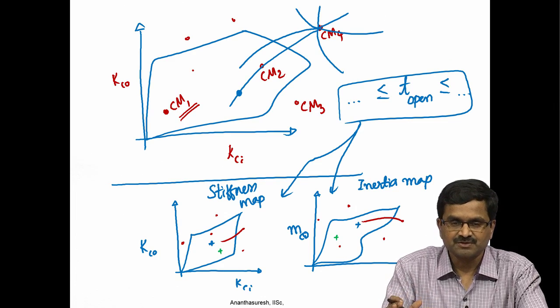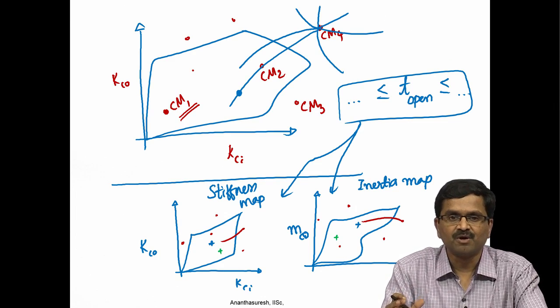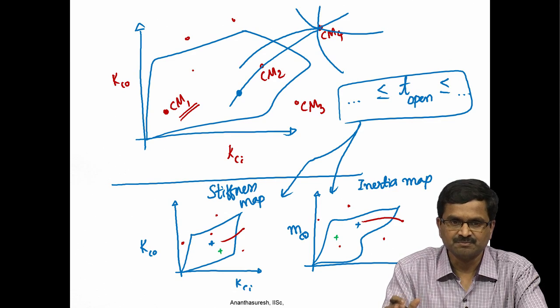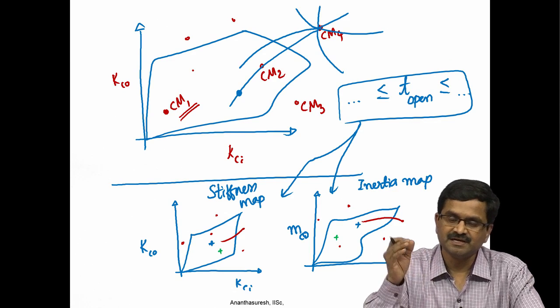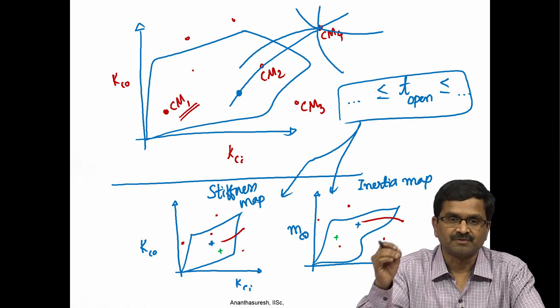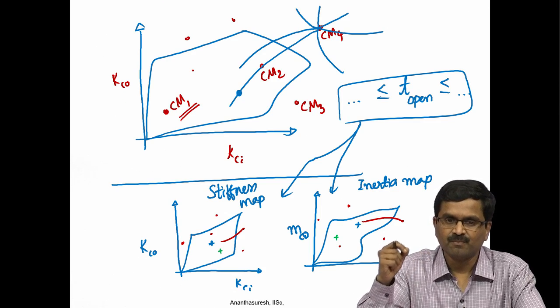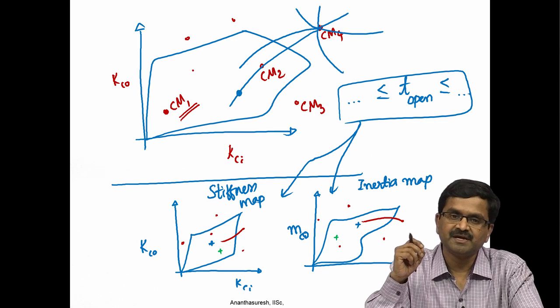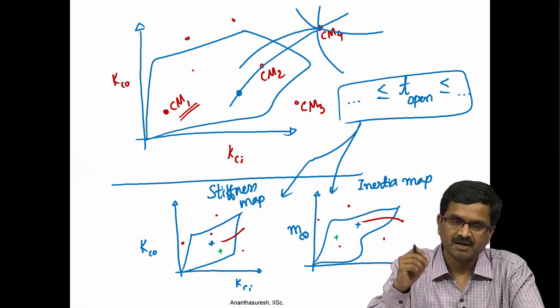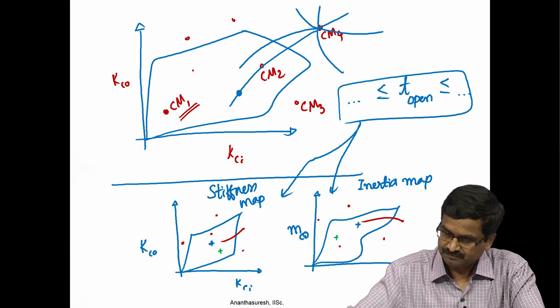All of this we have discussed so far applies to small displacement compliant mechanisms, meaning that instantaneously that is the properties they have. The spring lever model and spring mass lever model are both for instantaneous behavior of a compliant mechanism. But compliant mechanisms are known to undergo large displacements, so we need to consider that non-linearity also.